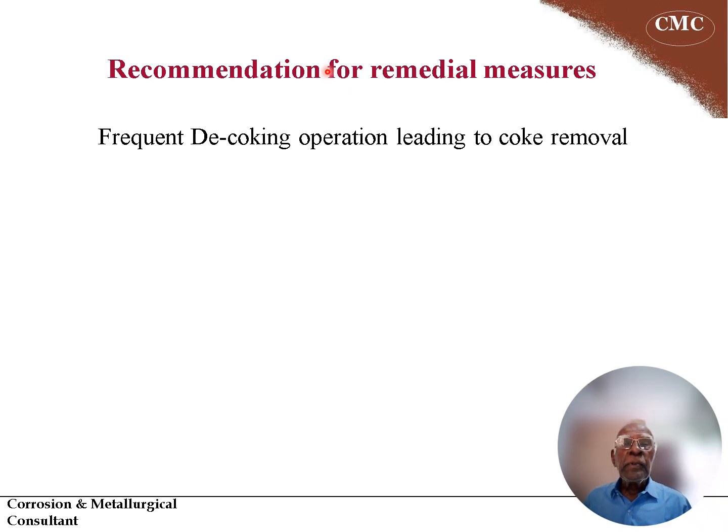These are the recommendations for remedial measures: frequent decoking operation, leading to coke removal. Decoking is a very common operation, something similar to frequent cleaning. This leads to downtime, but it is worth it. It will save the tubes. So decoking is a remedy for this particular problem.